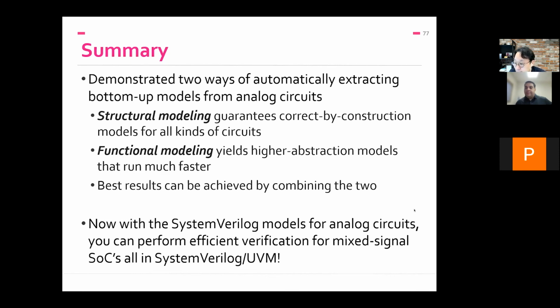There is a question about the incoming signal being current or voltage. I think I addressed that. My answer was that we can handle circuit-level models that really use the Kirchhoff equations to solve all the node voltages and branch currents. We can handle all the cases mentioned here, like multiple voltage sources being connected to one point and being switched, or having multiple voltage drivers.